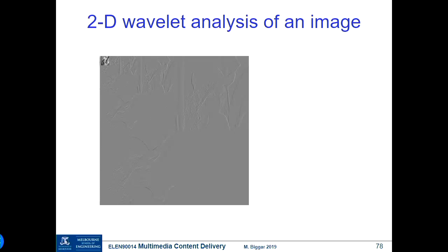Suppose we wanted to keep all the coefficients up to this one, because that's a reasonably large one, 14.75. Now, if we just scanned left to right, left to right, and we quantized so all of these small ones were 0, then we'd be on the 5th row of coefficients before we got to this one here.